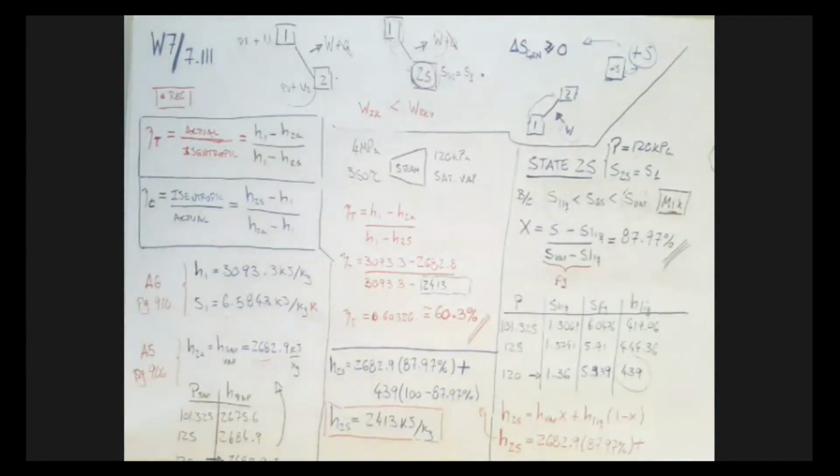What are our conclusions from this problem? Okay, our conclusions are, well, there are irreversibilities during this process, and they account for about 40% of what we could actually transform into useful energy. So we lose, okay, we don't destroy energy, that cannot happen because of the first law, right? But we stop the useful energy from being 100%, and we go down to 60%.